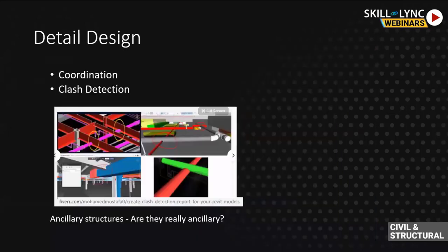One important aspect in detail design is clash detection, as I was mentioning. Because we have 3D software, say Revit, or we have EcoSim from Bentley, we have a very good understanding of how things can mess up on site. So we have this clash happening here. Now, if this is a beam and this is the first third of the beam and there is a pipe going through, I don't want my beam to have holes here.